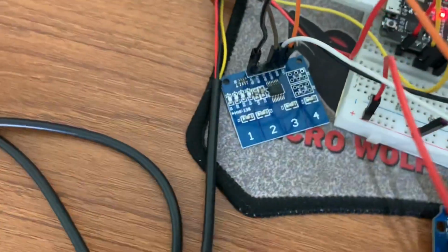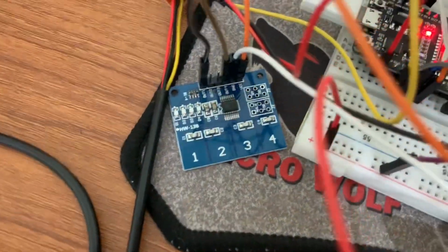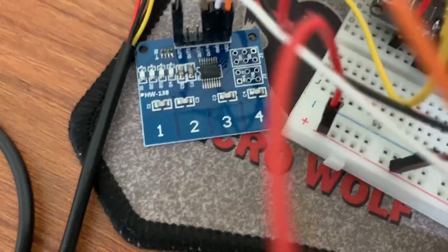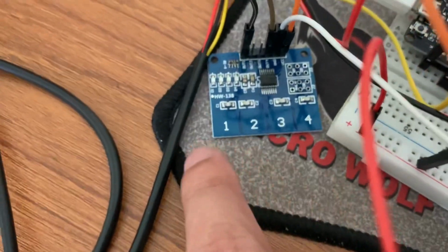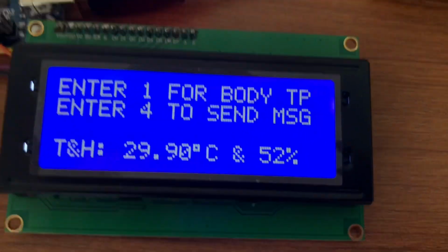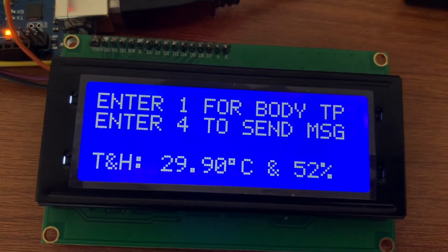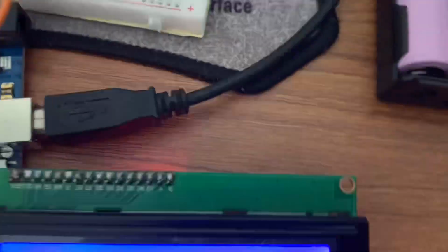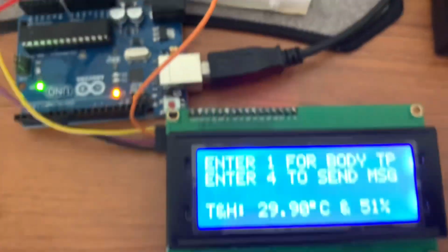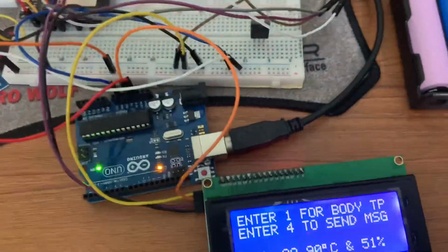And then for designing the user interface, to prompt the user, I have used the 4-channel touch capacitive sensor. I have used the 1st and the 4th channel. I will show you shortly in my demonstration. And finally, in order to design the user interface, I have used the 20x4 I2C LCD display. It has an I2C driver just below it. The use of the I2C driver allows me to work with only 4 wires, so I will get more ports available on my microcontroller to work with.